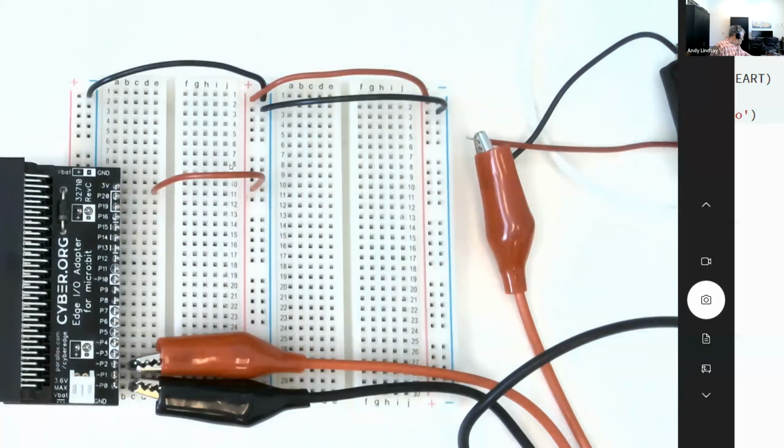And for extra credit, you can grab a battery out of your Microbit Go box and measure it by connecting the black probe to the negative or flat end of the battery and connecting the red probe to the positive end that has a bump.